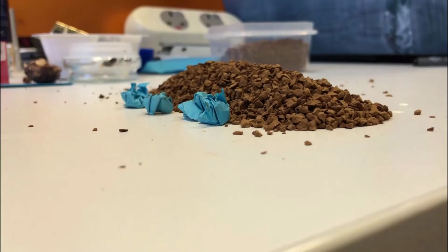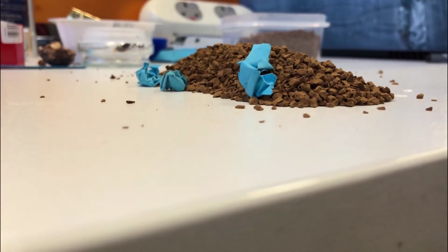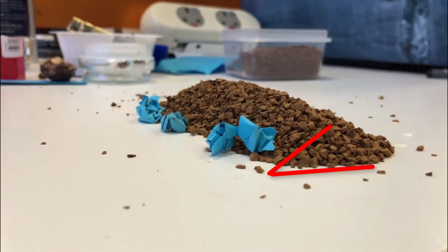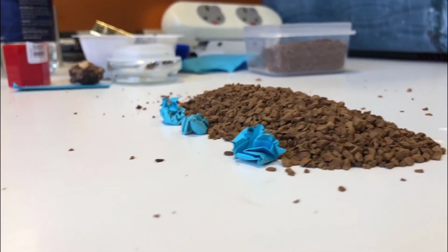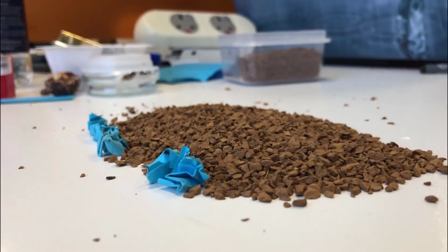However, the most significant failure was in Las Palmas tailing dam, which was used to contain tailings, toxic byproducts of mining. Each dam has a different angle of friction, which is the maximum angle that materials can accumulate before becoming unstable. In this case, it was lowered due to acceleration caused by the earthquake, which allowed the flow of tailings.